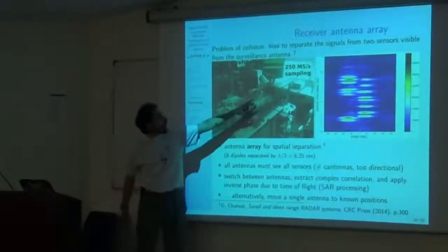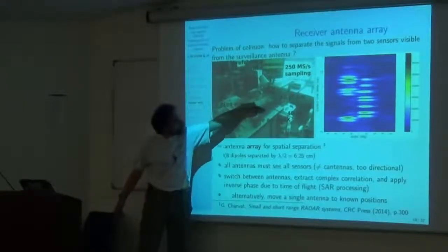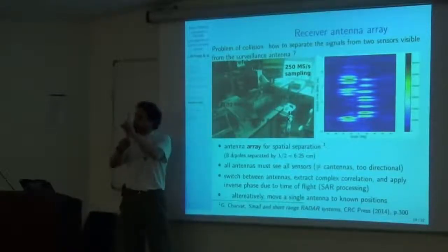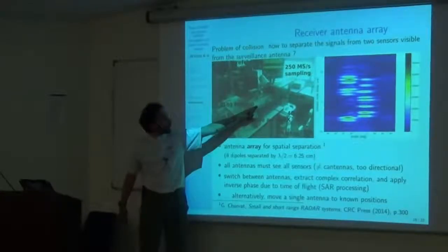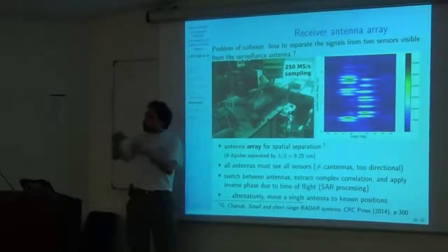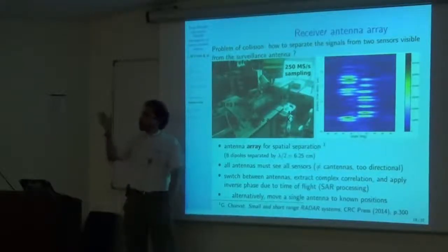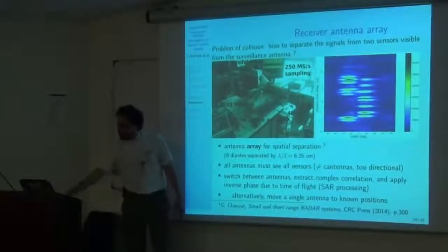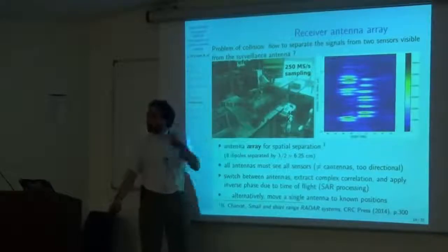So in my case, I have my Wi-Fi emitter over here, and I have 1, 2, 3, 4, 5, 6, 7, and 8 antennas. These are 8 dipole antennas located half a wavelength from a ground plane. And here I have a radio frequency switch that switches from one antenna to the other. Of course, it takes a lot of time to analyze because you need to measure 3 Wi-Fi channels multiplied by 8 antennas. When I say a lot of time, it takes 2 to 3 seconds to collect the data. But basically there is no reason for you to collect all the data at the same time. You don't need 8 receivers.